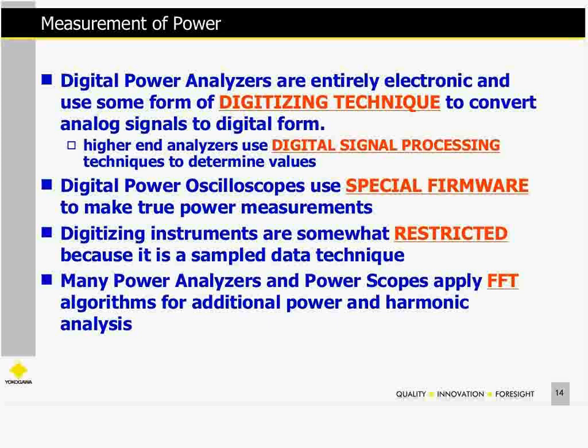The digitizing instruments are somewhat restricted because it is sampled data. We are digitizing the waveform. Most of the power analyzers and power scopes on the market today have an FFT algorithm used for additional analysis of the waveform, such as harmonic analysis. We do have another seminar totally based on harmonic analysis with power analyzers and scopes.